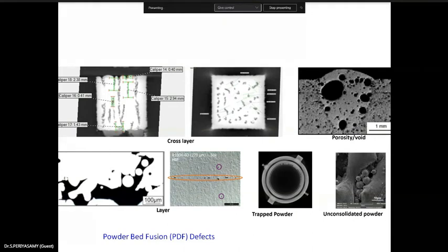Visually, if you are inspecting, it may look continuous, but you can't easily find the flaws. But in normal casting, if you pour the cast melted material in the mold, afterwards you can see some of the flaws with the open eye, the oxide layer, porosities, everything. Here you can't easily find that.